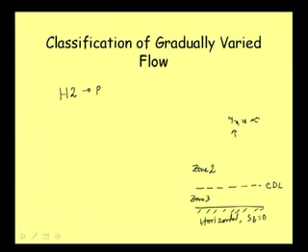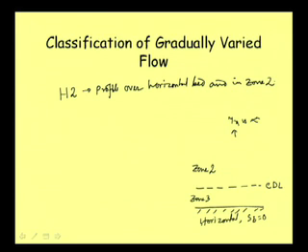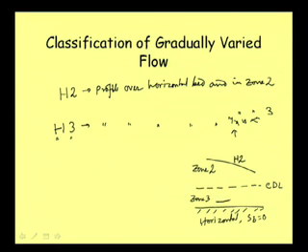So we can write this as a profile over horizontal bed and in zone 2. In this second zone the profile is a falling profile, that of course we will be discussing why, and this is H2. Then similarly H3, the profile over horizontal bed and in zone 3, that we call an H3 profile. That profile will be a rising profile, H3.